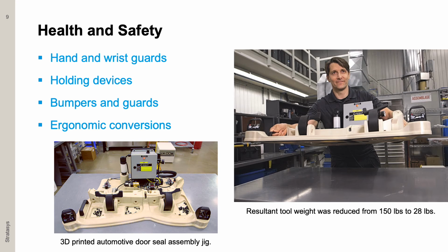Because additive manufacturing can make things faster and for less cost, it's a perfect solution for making tools more prevalent on the factory floor that enhance worker health and safety. In many cases, AM tools can be added to the inventory where there previously were none before due to cost, weight, or other factors that made them impractical. AM provides an easy and fast method of creating safety guards and other protective devices specifically tailored to the worker and/or task. Making tools with FDM thermoplastics enables the use of strong but lightweight materials. This means tools can be made that weigh a fraction of metal tooling. Lighter tools can reduce or eliminate injuries, strain, and lost work time due to repetitive use of heavy, bulky tools.